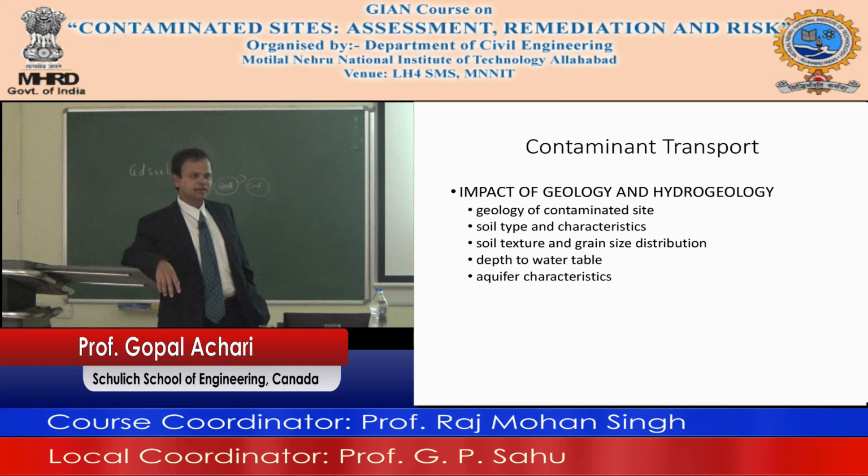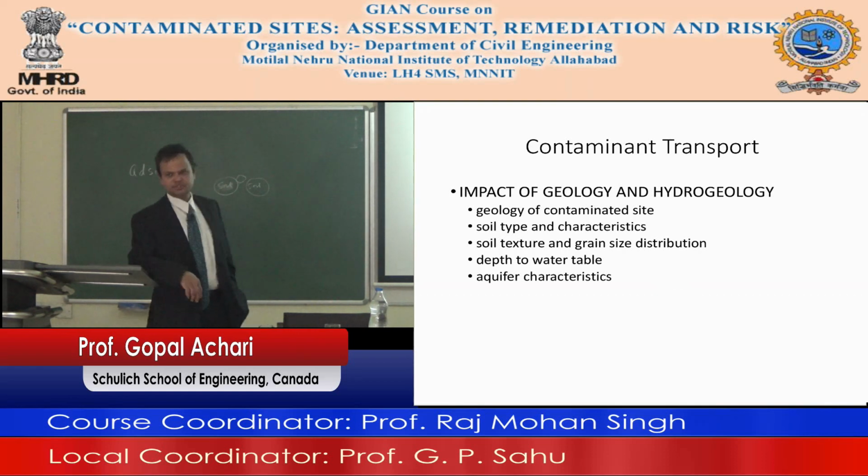So is it higher in silt than in sand, or is it lower, the capillary rise? Is it higher in sand or is it higher in silt? What is the answer? Higher in silt, right? Because of surface tension, right?